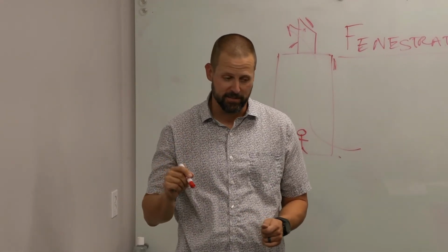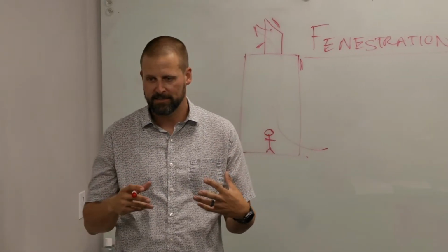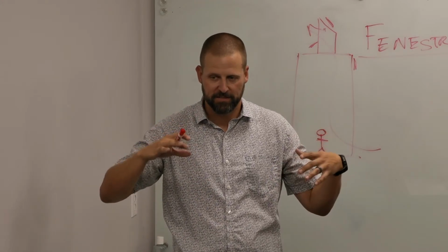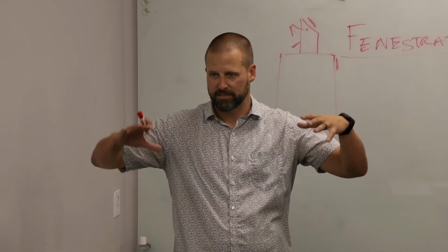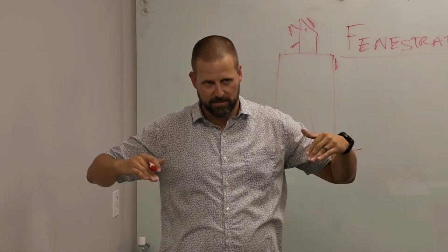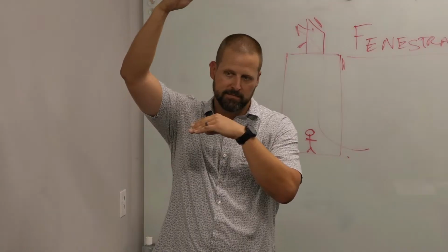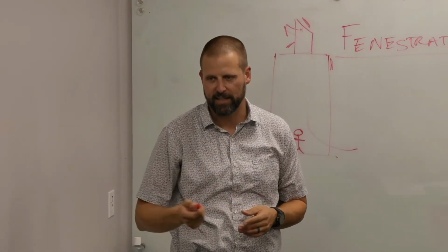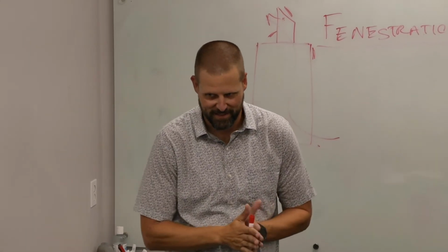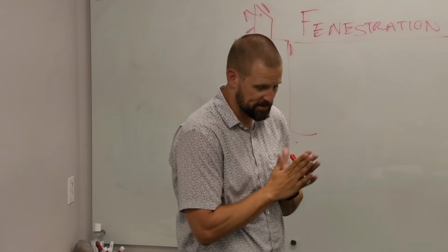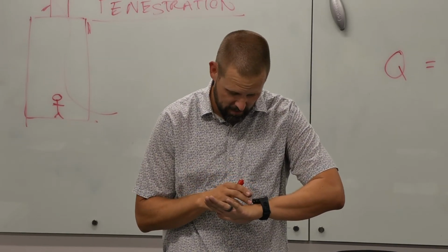We also use that in general load calc methodologies, which we'll talk about next week. We use a mixed space. For higher spaces, we look at stratification, which means we view the 6 feet that people are in differently than the 20 feet up in the air. So we look at high lobbies differently. From a code compliance standpoint though, I don't know if you can make that case. Let's keep going.